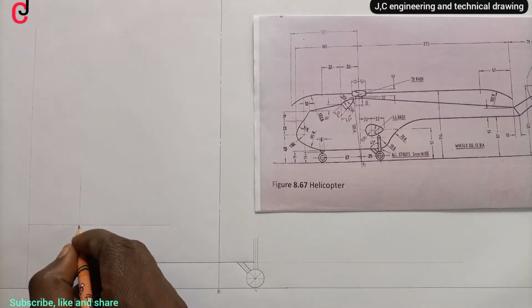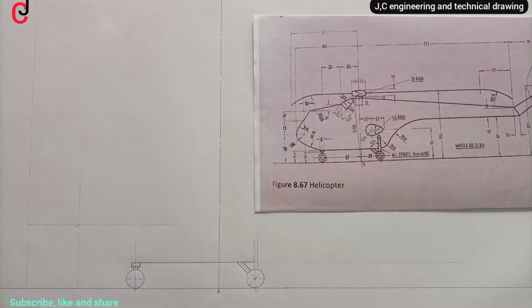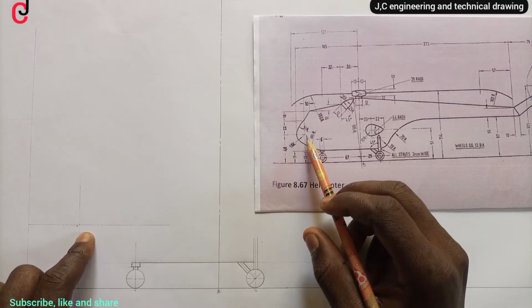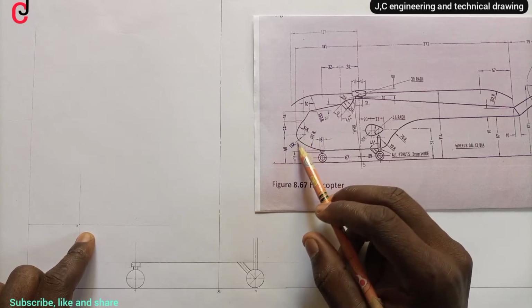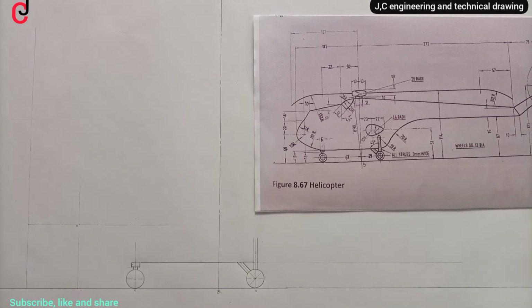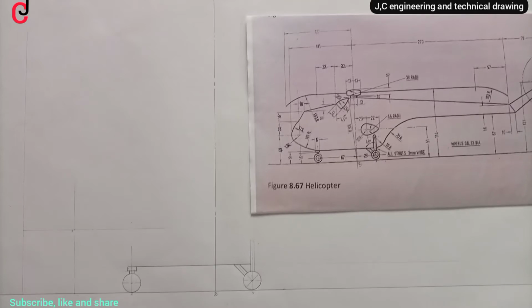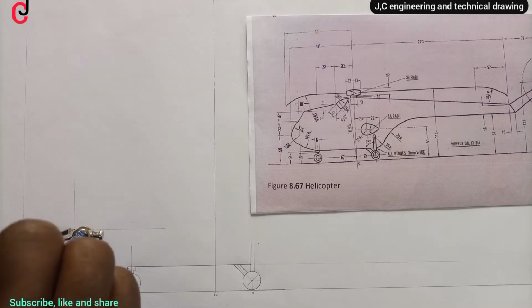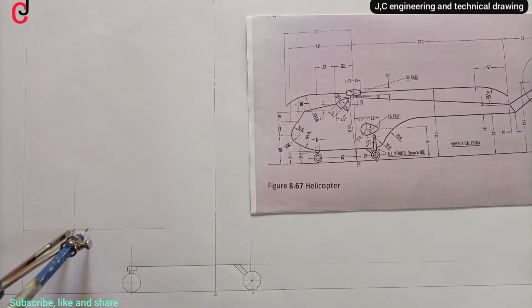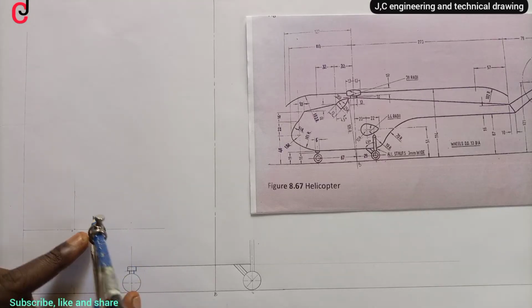Now you can see that this point here, where they intersect, you can call this point O. Now using point O, we'll open our compass to 13 millimeter radius. So we succeeded in picking 13 millimeter radius with our compass. We'll place it at point O and we'll scribe an arc on our horizontal line. Now using that point on our horizontal line, we'll draw a semicircle.